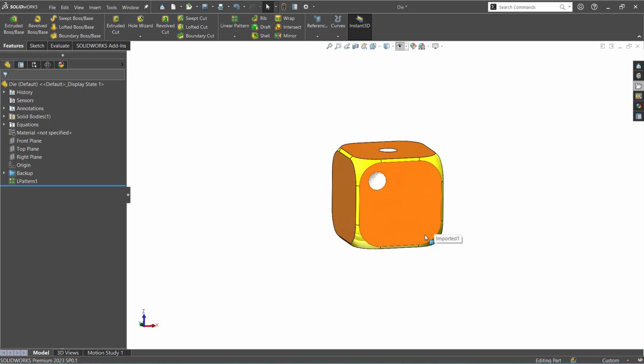Linear pattern. Okay. But if you select linear pattern, it will go with this direction and this direction, right? How can you have 3? We cannot do a diagonal center line. There is another option, that is the sketch based feature that we can try. Shall we try that? Yes.